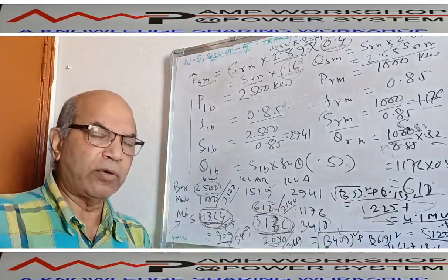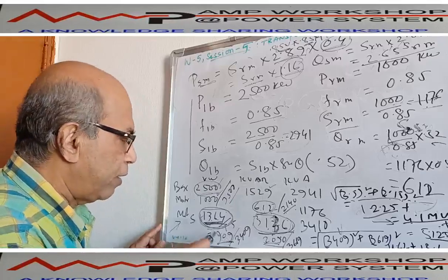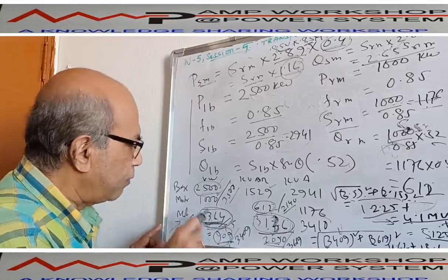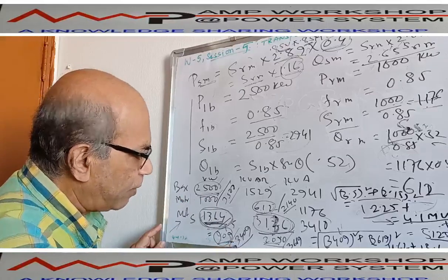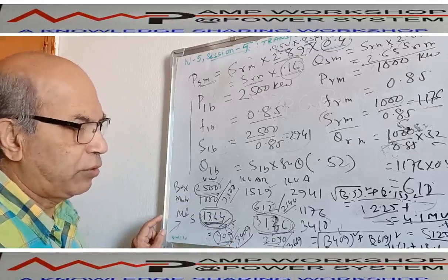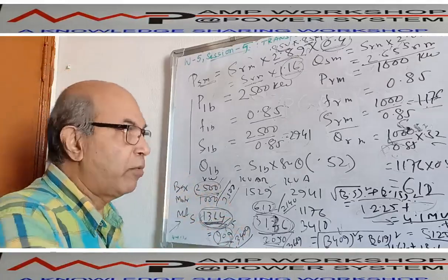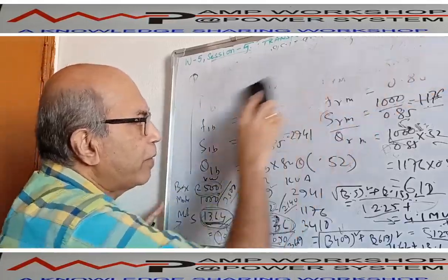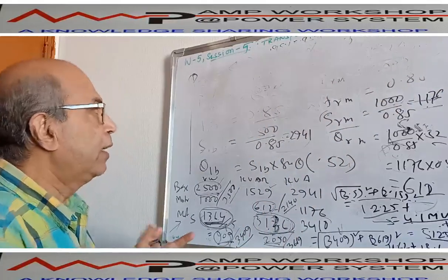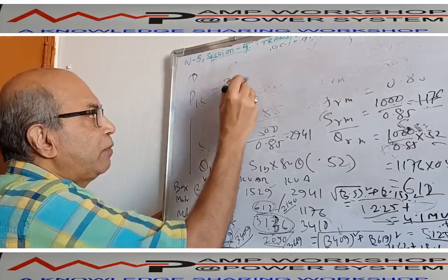To calculate the motor starting kVA requirement, we have calculated the motor starting kVA requirement. In that case, the base load is equal to how much? 2500. So total coming how much? Kilowatt is coming 3409. Okay, 3409 is during starting of the motor. Kilowatt requirement is 3409. Write it down over here. So during starting, our total power requirement P1 is equal to 3409.